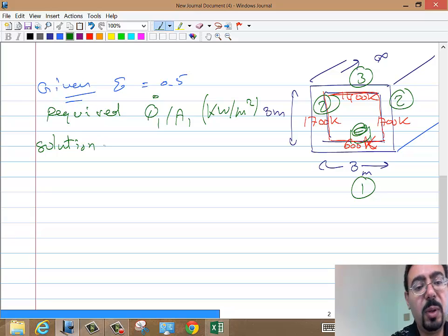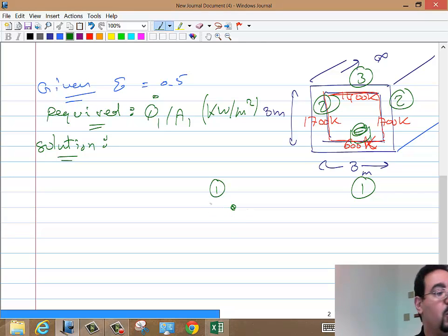So to solve this problem, and that's the same for conduction and convection, you need to make an equivalent electric resistance network to make your life easier. So basically you say, here's my surface 1, sitting at E_b1, and then there is the surface resistance to radiation, (1 minus epsilon 1) over (area 1 epsilon 1), and then you will have his J1.